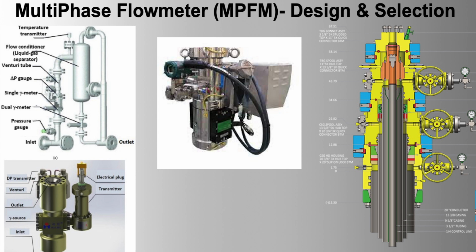3. Enhanced processing efficiency. Optimized separation. Knowing the composition of incoming fluids allows for better tuning of separation processes and targeted chemical treatments to enhance separation efficiency. Improved emulsion breaking. Real-time data on water cut and oil quality aids in adjusting demulsifier dosing to improve emulsion breaking and separation efficiency.